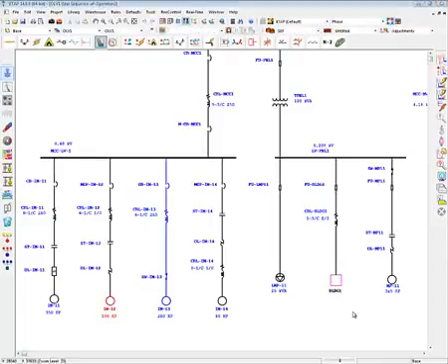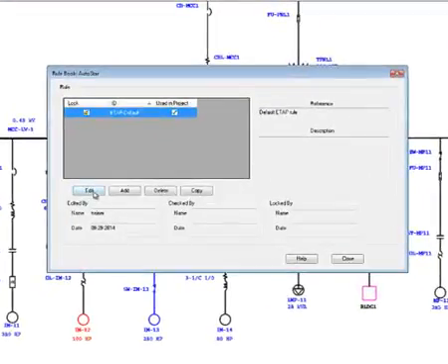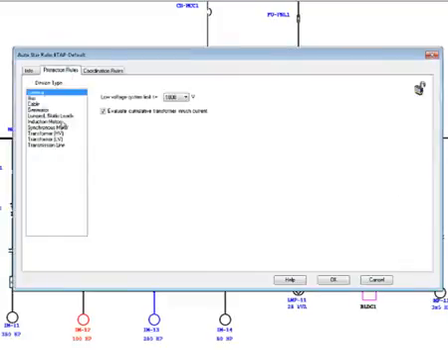So I have the same system here, but I will use a different technique to do protection and coordination and analyze my results. The graphics just look different because of the enhancements we have done in the future release of ETAP. So if I select this motor and press the button we call star evaluation, or auto star evaluation, it will run an evaluation based on some predefined rules from the rule book.